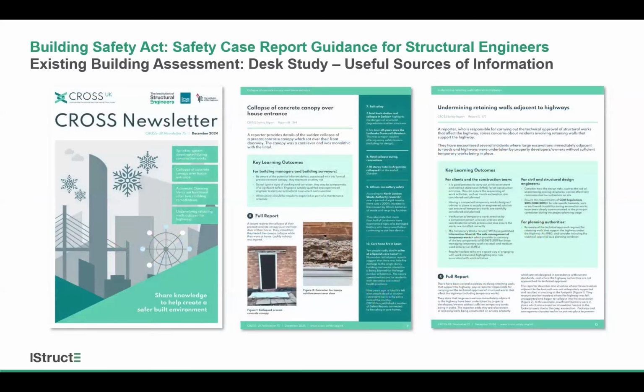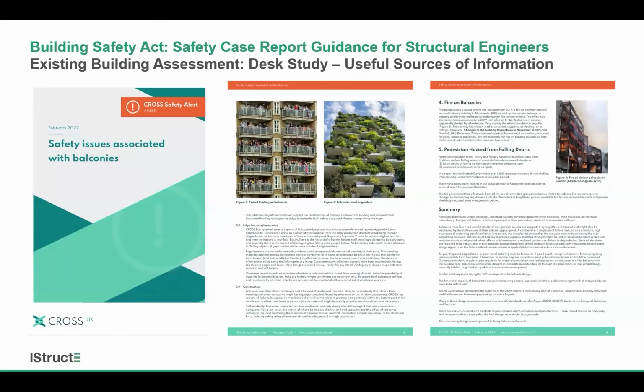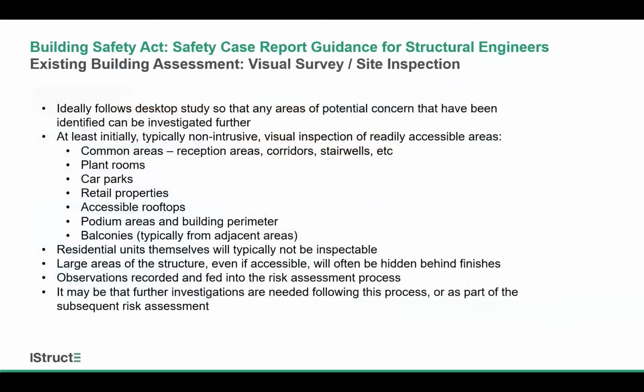I mentioned the cross newsletters. These are effectively a prerequisite for anyone who's doing anything to do with the Building Safety Act, which is effectively all of us. These are very good at highlighting common issues and common concerns. Not everything will obviously be directly relevant to a structural risk assessment that you might be doing, but there's definitely things in here around balconies and transfer slabs and various common issues that are well worth being aware of. And that's true of the safety alerts as well, which highlight specific concerns. So I definitely recommend that you're staying on top of these and signed up.